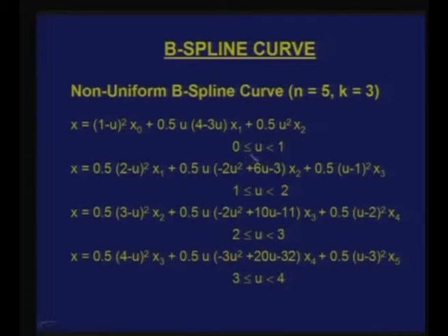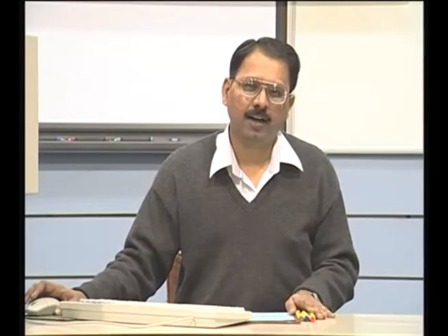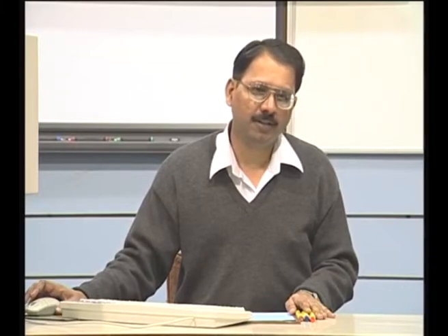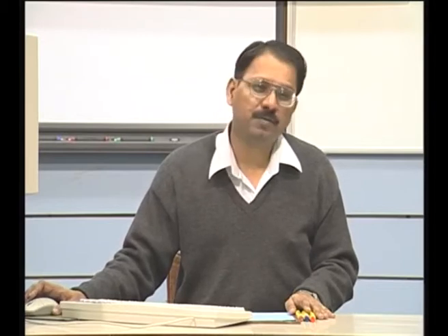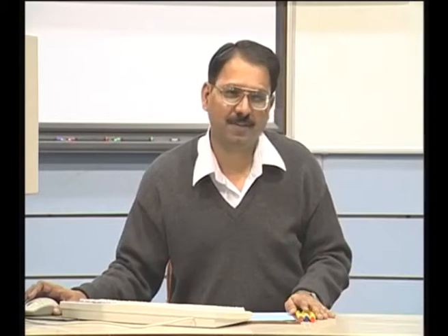Now, if I choose, for example, k is equal to 4, then I will have a different equation which will have terms x0, x1, x2 as well as x3, and all these values will change. So, I have different functions which define the curve when k is equal to 4. And if I want to plot the curve for display purposes, or take a cutting tool along this particular curve, and evaluate a number of points on the curve, then you need to use different equations for the different segments of the curve.